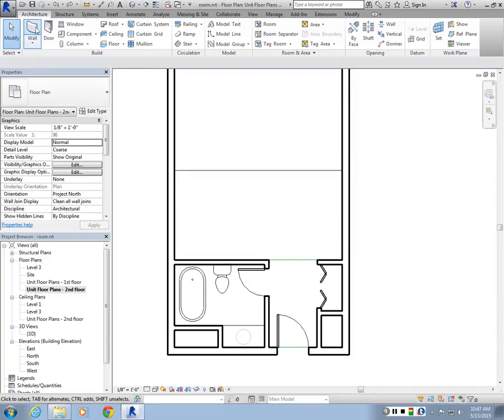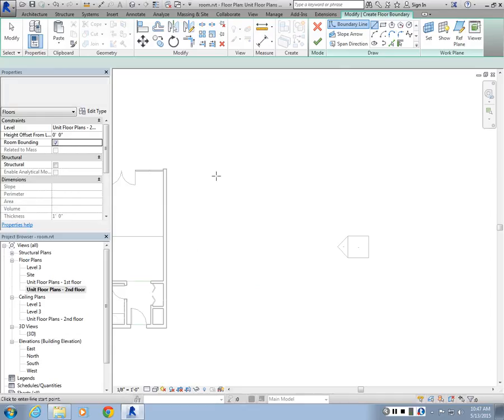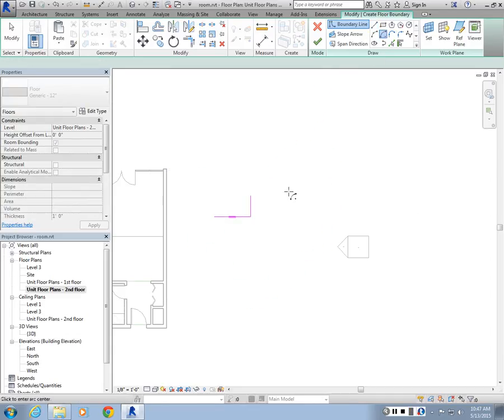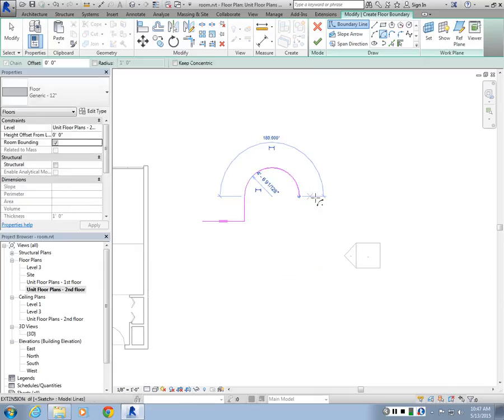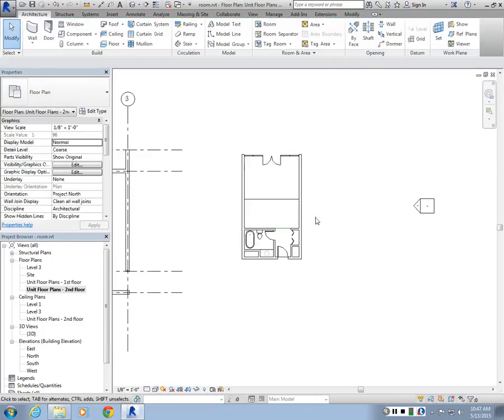Yes, good question. So if yours are curved, you can draft them using the arcs or splines. There are different ways of drawing them, right? So if, let's say, it's coming in, going up, then you may want to put an arc here. So you can specify the center. There's probably a center you can grab, right? There may be a wall already. Or you can also use the pick walls command to extract that outline directly from the walls. Okay? Any other questions about floors?